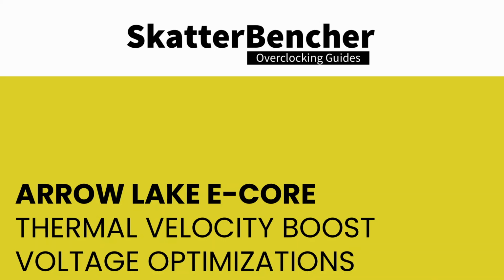Thermal velocity boost voltage optimizations is an Intel technology that takes advantage of the fact that CPUs need less voltage to run at a certain frequency when the operating temperature is lower. So as your CPU decreases in temperature, it will also reduce the operating voltage for a given frequency. When you're trying to manually tune the voltage of your Arrow Lake CPU, it's prudent to disable this technology.